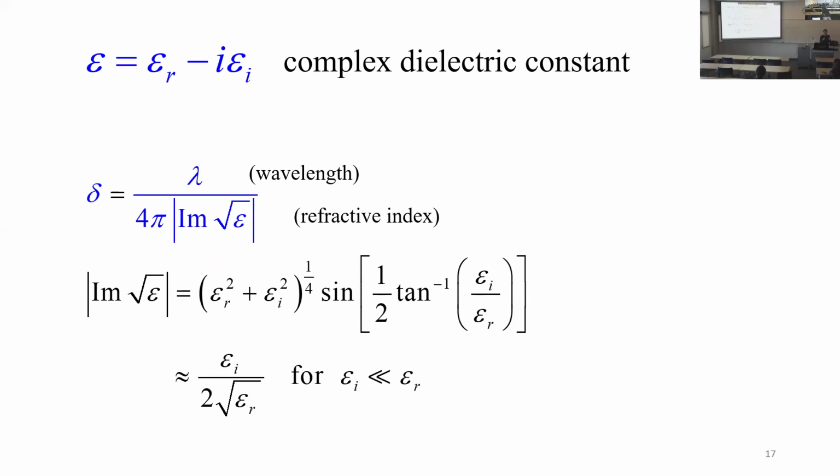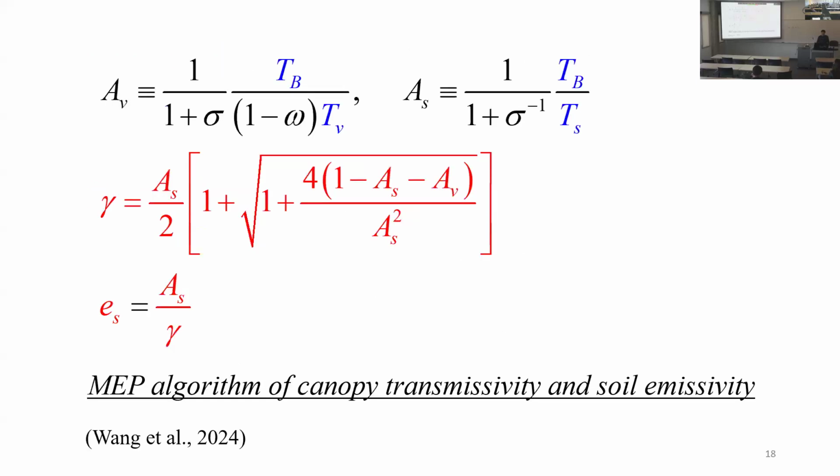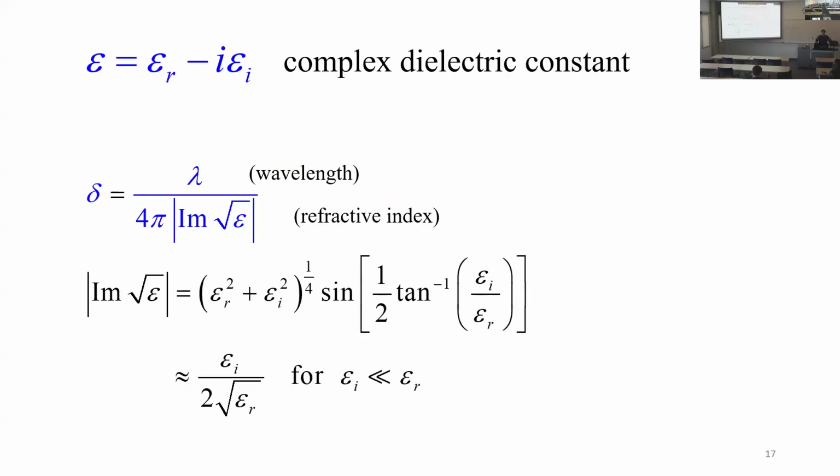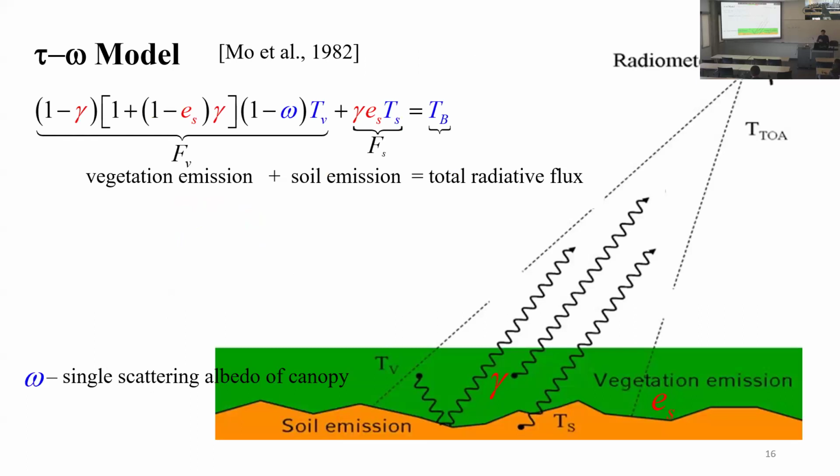The dielectric constant is a material property of dielectrics. It has a real part and an imaginary part, which is well known. From there, we can calculate the penetration depth of the EM wave in this material. That gave us a length scale. Then we use that in the formulation, the optimization, of the radiative diffusivity, which is then used to formulate the radiative inertia in a way analogous to the thermal inertia. So they have this correspondence. Then we used all this theory, this concept, to formulate the problem, so we go back to our problem here.